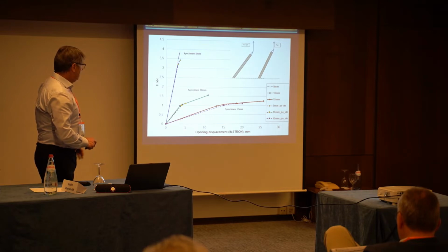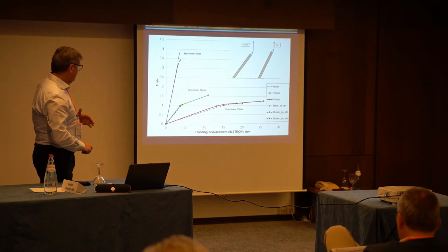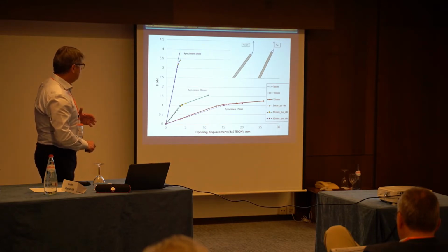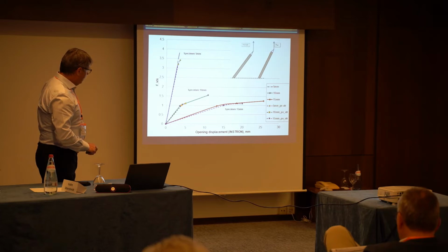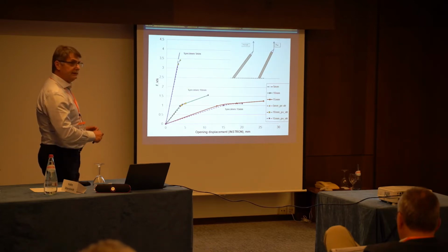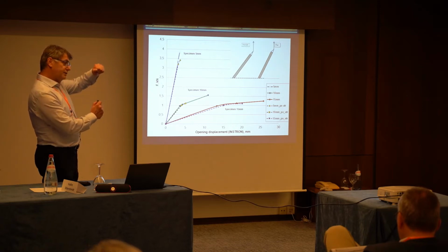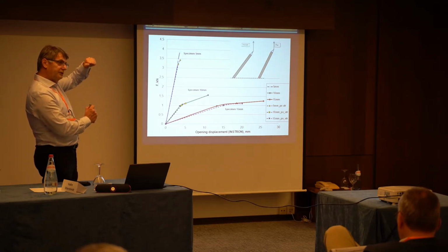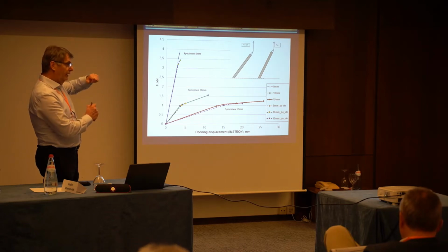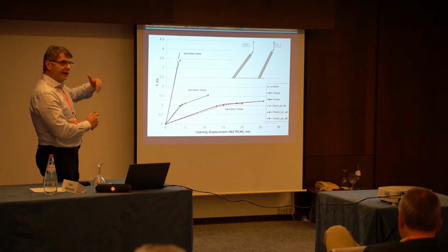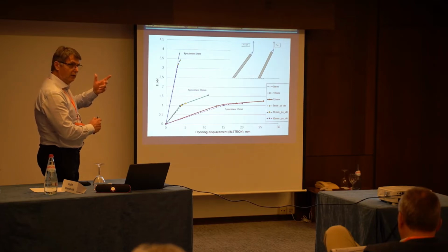And here now we follow this opening. It starts from 0 to the maximum load. For 10 millimeters we get to 1, and then already come here into the plasticity range. That means when you load once, you will never come back to the same point. So if you load in this way, you will have, let's say, low cycle fatigue behavior locally.